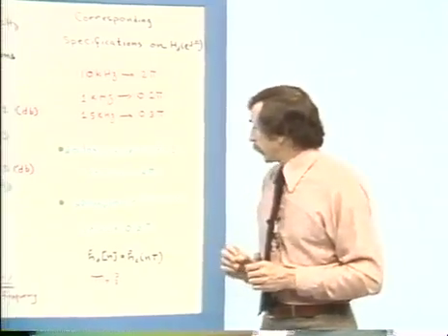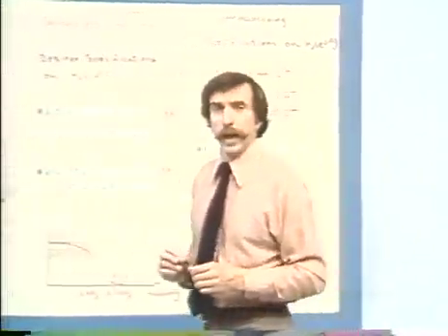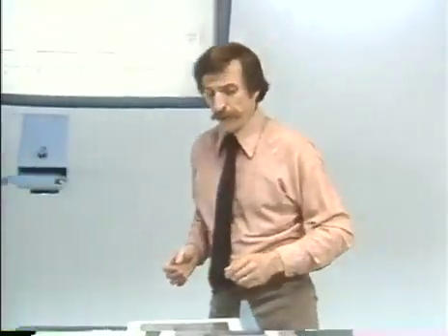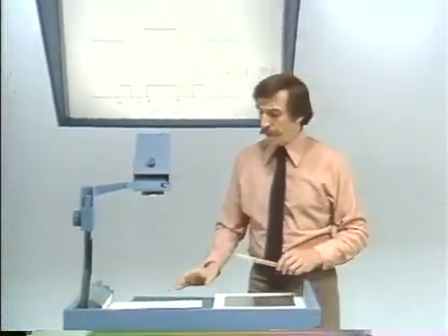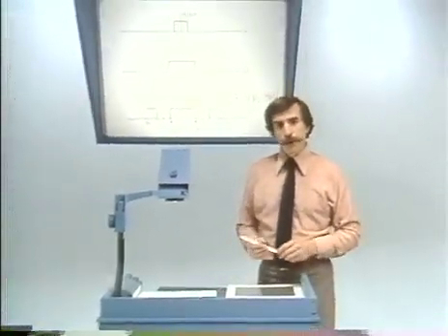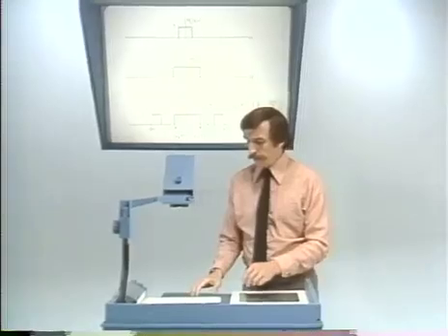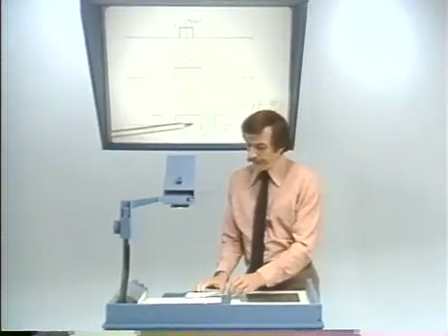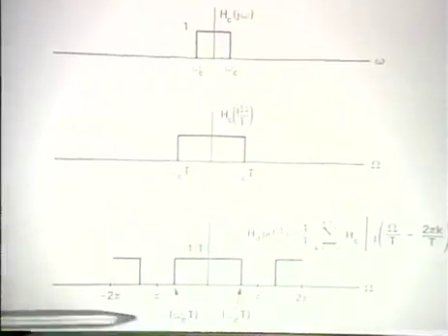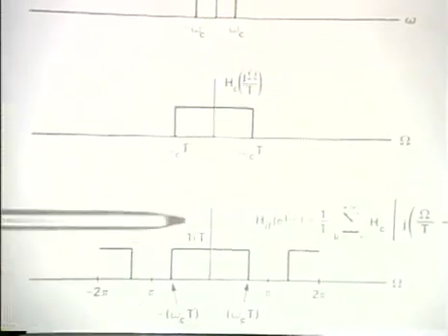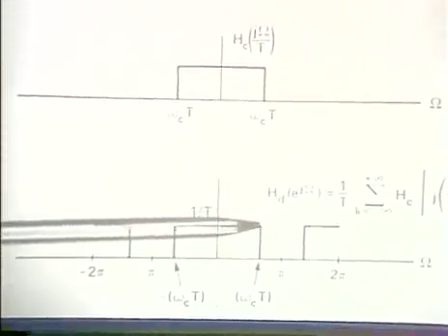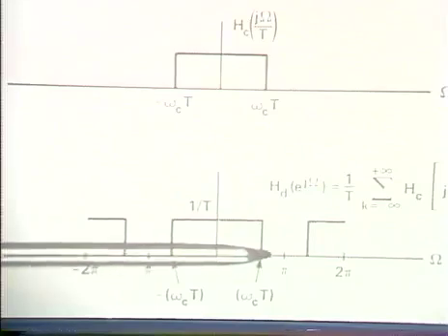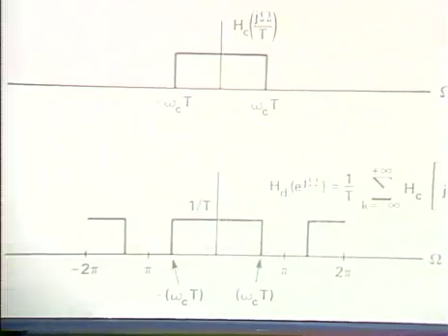All right, but let's now look at where we are in our design procedure and specifically what we need to do in order to design the digital Butterworth filter. We have a set of specifications relating essentially to how we want the pass band and the stop band of the digital filter to behave.